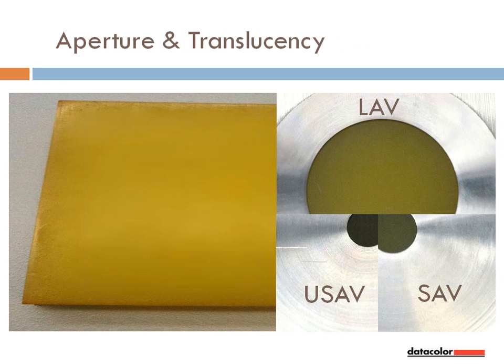Beware of mixing aperture sizes. It's not much of a problem with samples that are opaque at their surface, like a completely opaque coating, but for translucent samples, even stacked or folded to opacity, the differences can be huge.